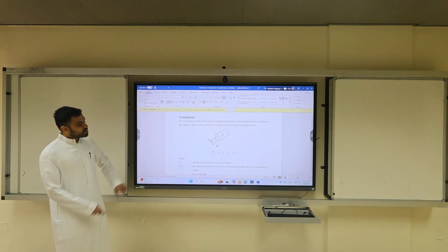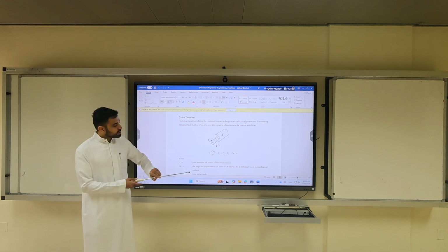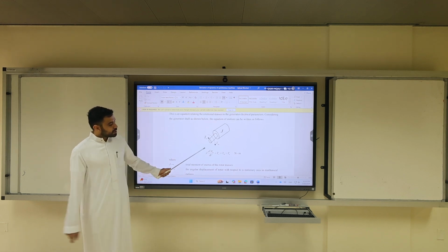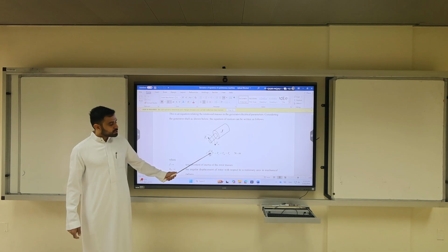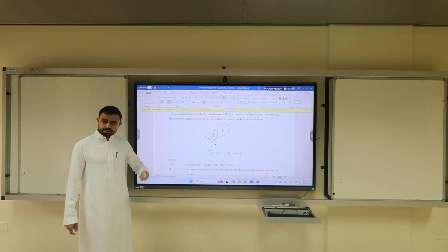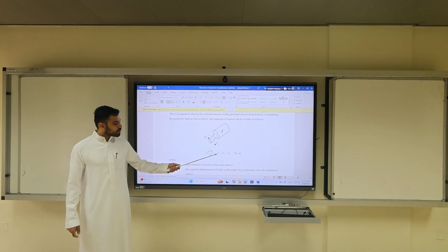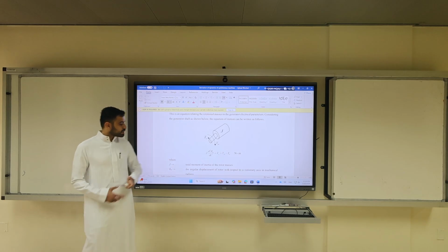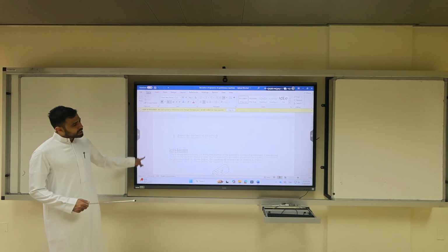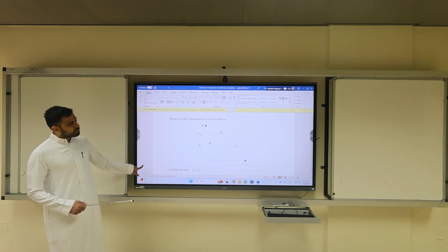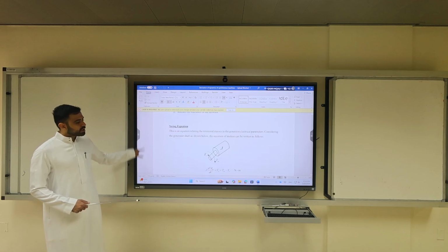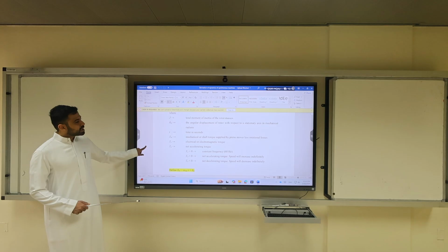The swing equation is inertia times the rate of change, the second moment, or the acceleration of the angle. So take the derivative of the angle function 2 times would equal to the acceleration torque, which is mechanical minus electrical. Keep in mind that measuring the torque is much easier. So these are the quantities.